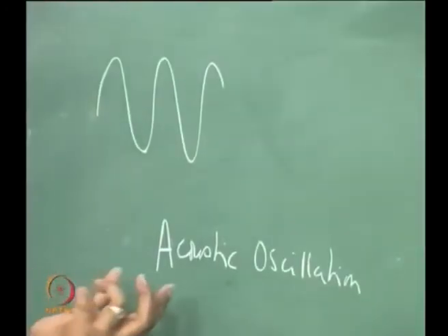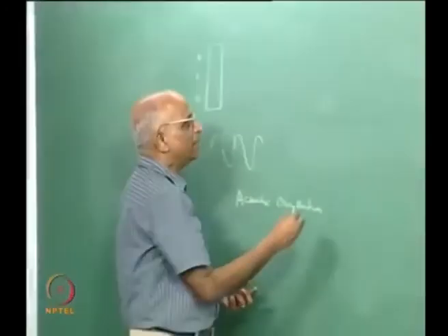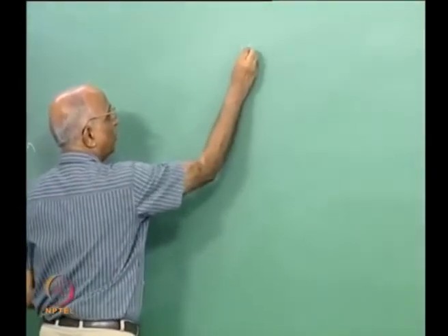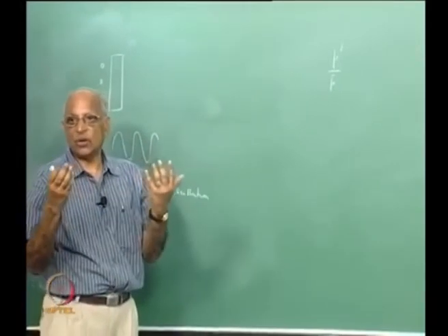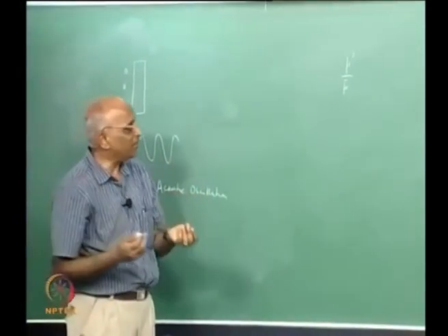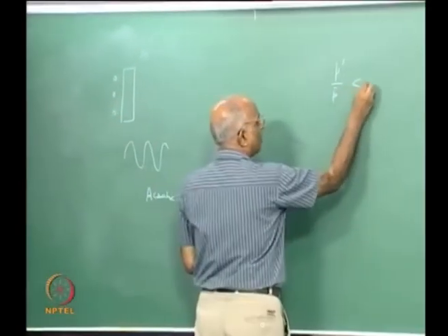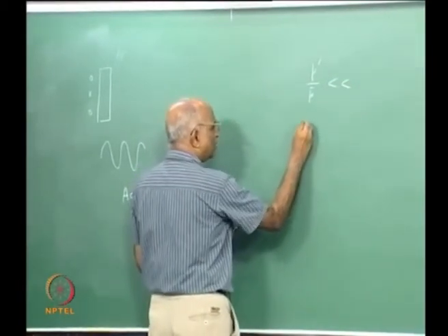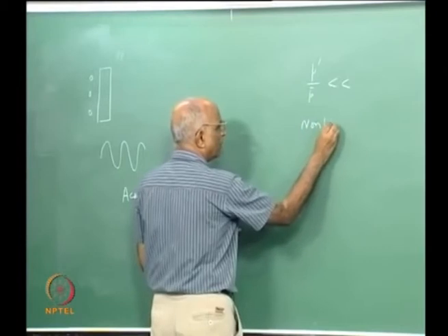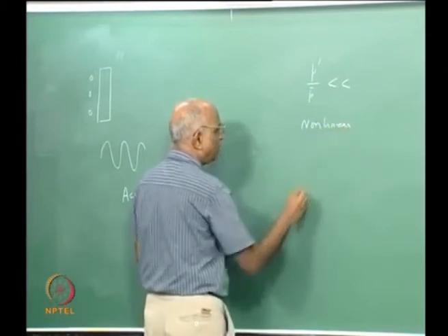Well, what is the characteristic of acoustic oscillation? The pressure perturbations are small compared to the mean value of pressure. Like when I talk, it is all isentropic and the pressure changes are very small, but under certain conditions the oscillations become non-linear. What do you mean by non-linear?